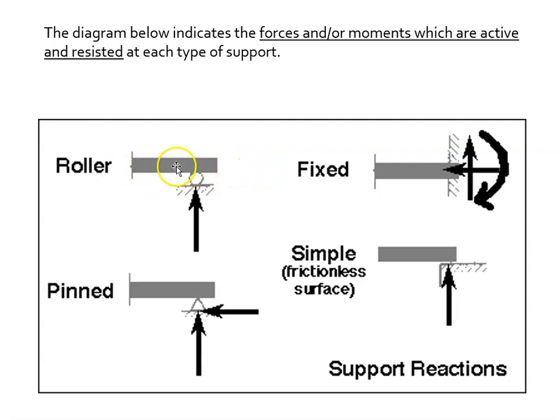This is a situation that is used in a bridge, for instance, and outdoor stadium arenas with big massive roofs. They live out in the elements. They experience freezing temperatures and probably temperatures of 150 degrees when it gets so hot directly on a bridge or on a roof. So massive swings in temperature make things move, and sometimes rollers in situations like that are a good thing because they allow things to expand and contract.